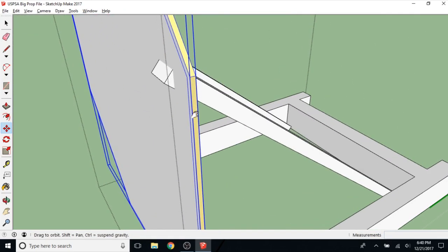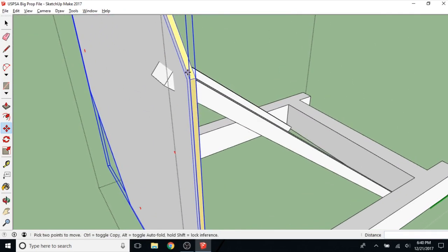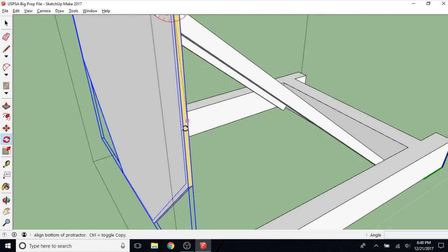And this is going to be a little strange. So this is where we're going to actually use the rotate command. We want to rotate it around this spot. We're going to rotate around the red axis. So we're going to click here to start with, because that's the point where we want to rotate it around, on the corner of the target here.